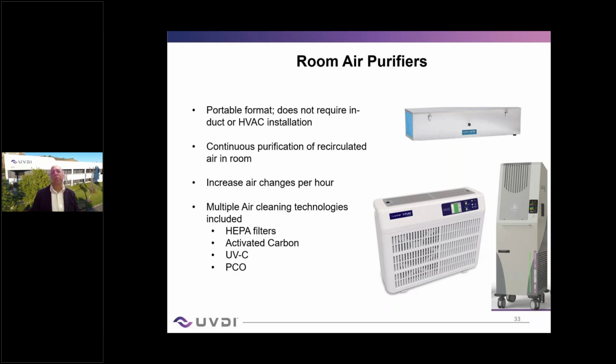So you would find a whole range of room air purifiers in the market, but you have to see whether it's a certified HEPA or they're just making claims that it's 99%. And sometimes you want something which does a bit of everything. The advantage of room air purifiers is that they really work well in a recirculation. Don't expect very high single pass removal rates.